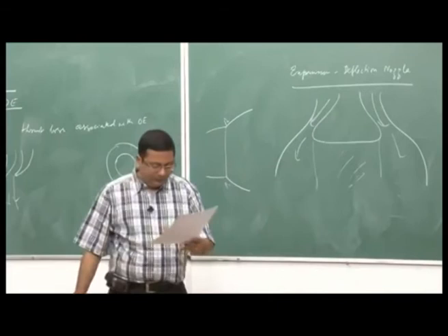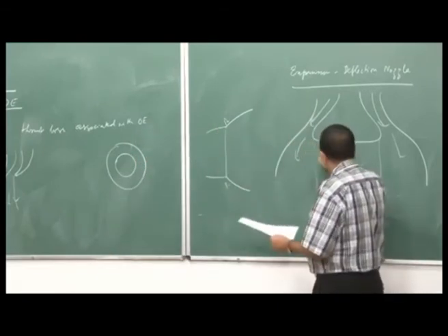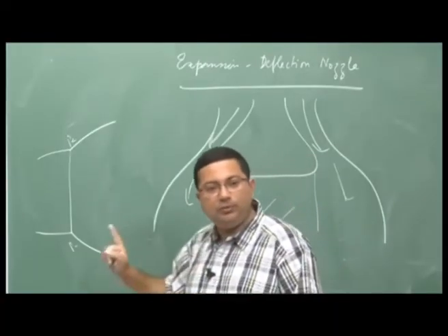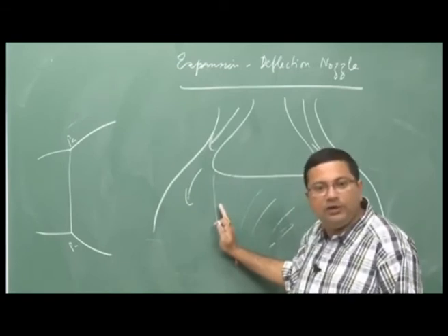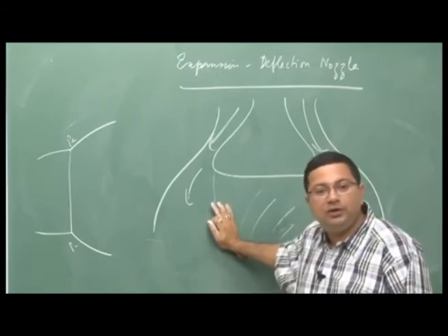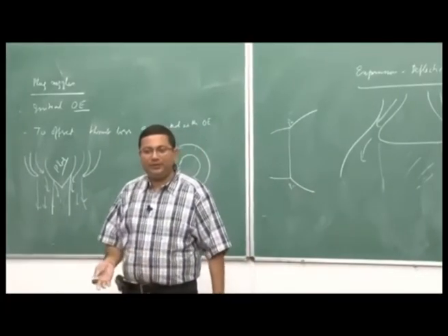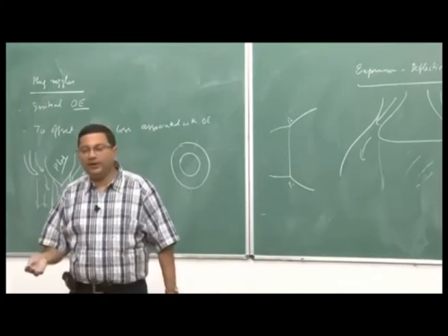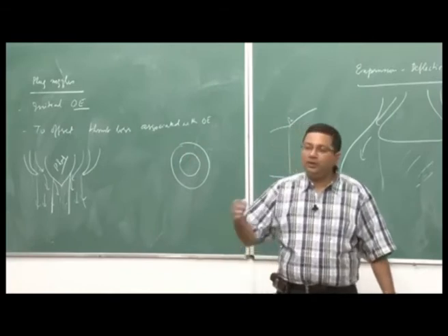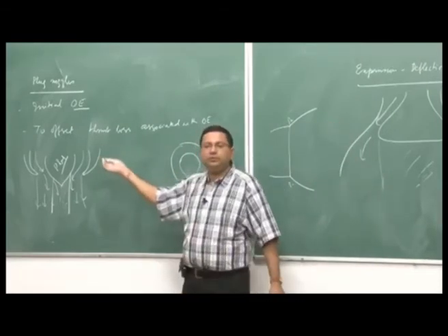This also, the flow here also expands along a corner, and because of this expansion it can expand to the actual atmospheric pressure, right. So, it expands to the actual atmospheric pressure. Therefore, the over expansion is eliminated. So, if you eliminate the over expansion, the shock induced losses, once again I would like to reiterate, will be reduced, and because of that the performance will be better.